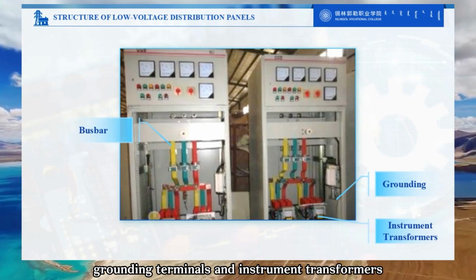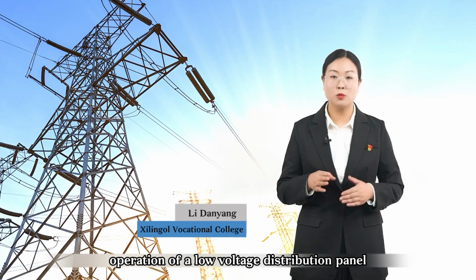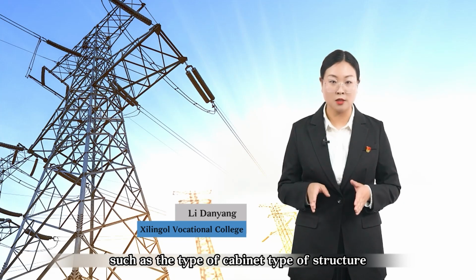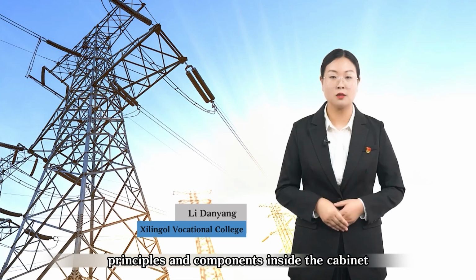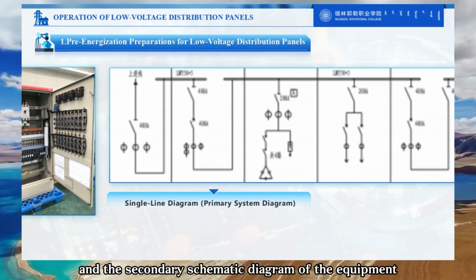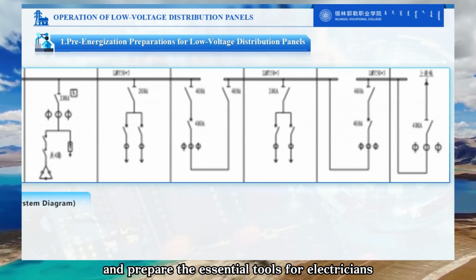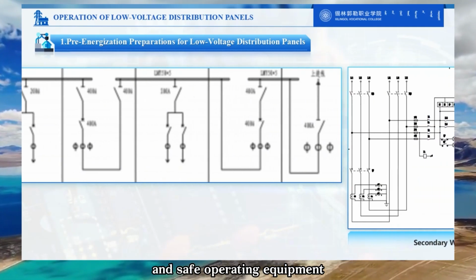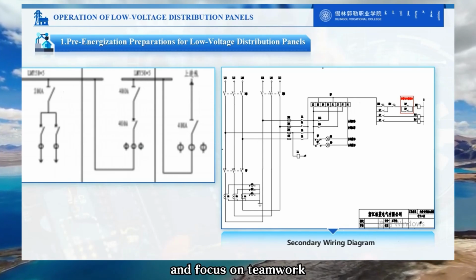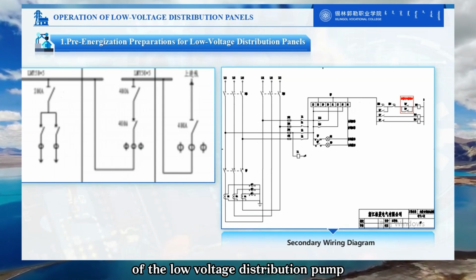terminals, and instrument transformers. In actual work, before performing the power-on operation of a low-voltage distribution panel, we need to be sufficiently familiar with the equipment we are operating, such as the type of cabinet, type of structure, principles, and components inside the cabinet. At the same time, we also need to prepare the primary system diagram and the secondary schematic diagram of the equipment, perform pre-power-on checks of the distribution cabinet, and prepare the essential tools for electricians and safe operating equipment. Here, the teacher must further emphasize, you must pay attention to not working alone and focus on teamwork. Below, based on the video, let's learn about the specific operation of the low-voltage distribution panel.